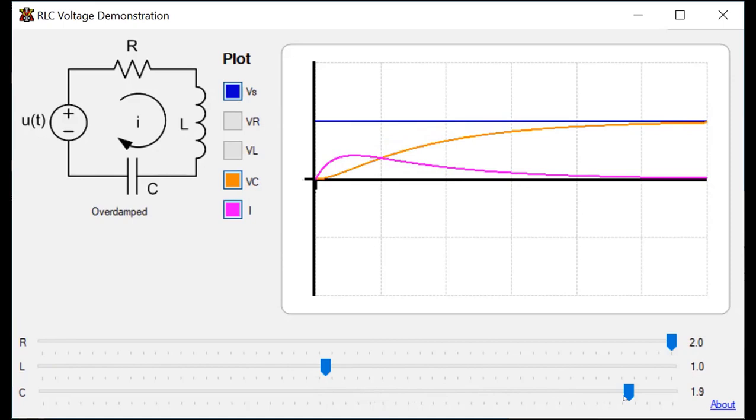it takes longer and longer, the capacitor is huge, it takes longer and longer for it to fill up with charge, then you can imagine it's going to take longer and longer for everything to approach its final values. It's less likely to oscillate because we're now being dominated by the value of this capacitor. It's almost looking like a first order circuit. In the limit, if we drop that inductor to close to 0 and make that capacitor really, really large, it would look almost like a first order circuit where we just have a resistor and a capacitor.